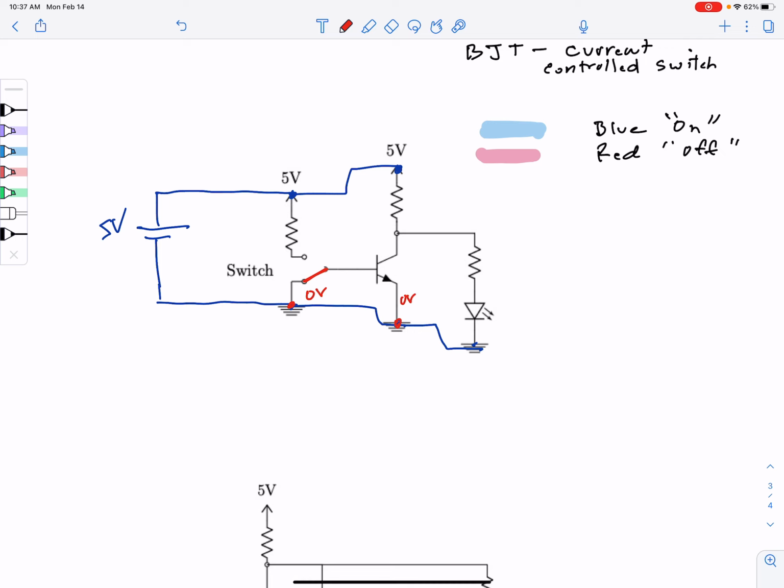That means, typically through a transistor, if you have current flowing into the base, this middle terminal is called the base of a BJT, there'll be a slight voltage drop across the transistor. But since there's no voltage drop, right, this is 0 volts, 0 minus 0 is 0. Since there's no voltage drop there, the current coming into here is 0.